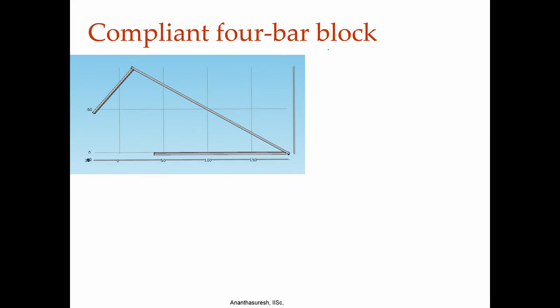And then they also go to the 4 bar linkage, but now it is compliant. So, this is compliant, this is compliant, but this one they want it to be rigid, that this segment. Okay. So, now if we were to fix it here and fix it here, these two are compliant ones, this is compliant, this is compliant, in between you have a rigid one.